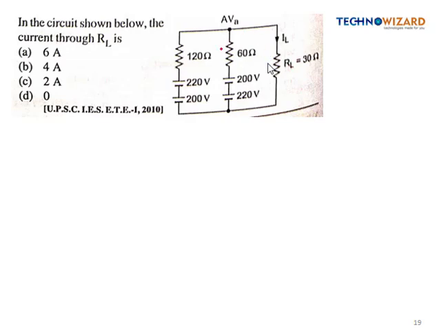So simply we can find out the value of current using the nodal analysis, right? So this is a node, and suppose here the voltage is V1 at this node, right? So in the nodal we have to mark the current in the outgoing direction. So suppose this is the current direction, right? So here the current will come like this, but this voltage source is going to deliver the current in this direction, which is going to oppose this current.